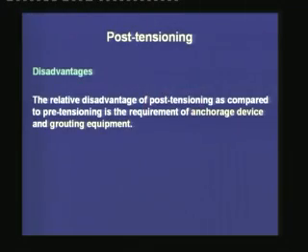Now, there are some disadvantages of post-tensioning as compared to pre-tensioning. In the post-tensioning operation, we need much more developed anchorage devices as compared to pre-tensioning. In pre-tensioning, the anchorage devices are small. They are usually just some chuck assemblies for the individual strands, but in the post-tensioning operation, we shall see that we shall use heavy duty anchorage blocks for the transfer of pre-stress from the steel to the concrete.